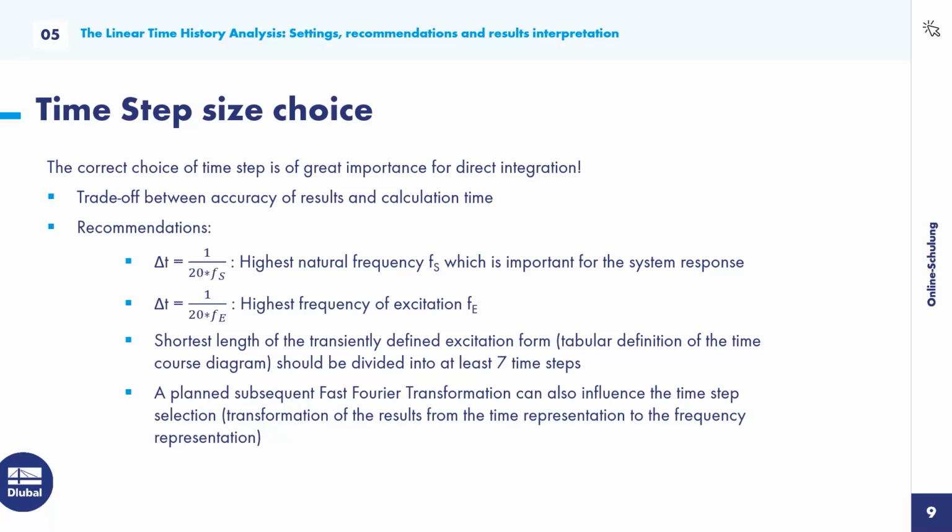For today, I will go into something that did excite me for a bit. And that's the so-called fast Fourier transformation. So what we want to do here is take the results out of RFEM in the end, and look at the results not in the time domain, but in the frequency domain. And this fast Fourier transformation has some things you have to consider or take into account beforehand,